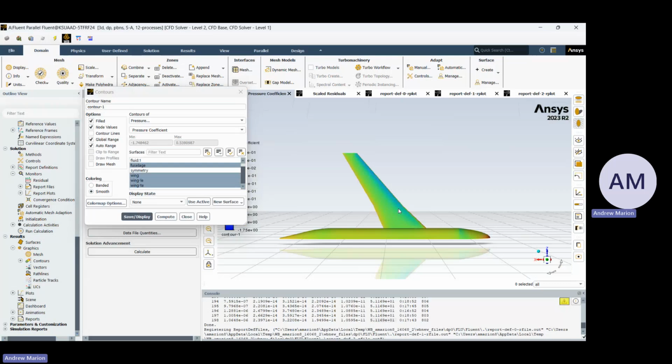wing, what are they called? Winglets. Where you see the very tip of the wing curves up a little bit. That little curve can help prevent spillage of the high pressure air under the wing trying to get to the top low pressure, and it will cut down on the wingtip vortices, which will cut down on drag, and also make it easier for planes behind you to land. There's also other ways you can deal with it.